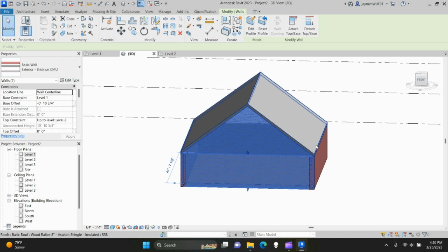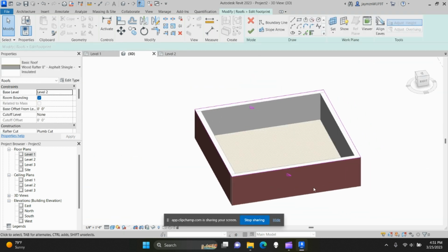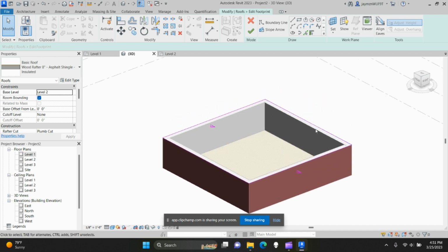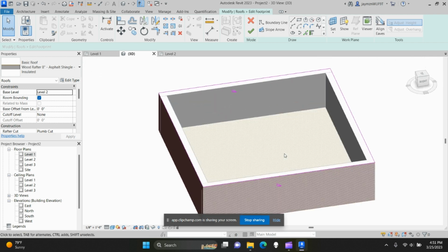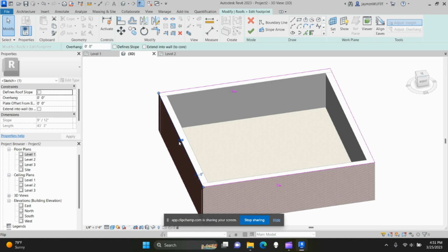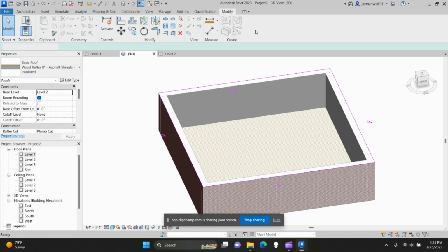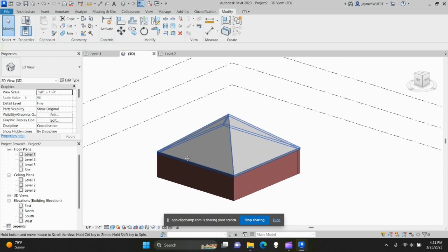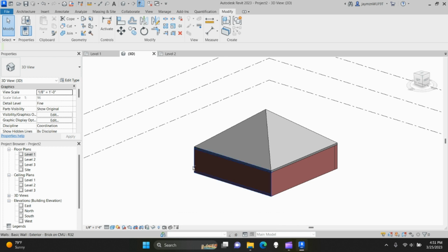So we're going to click this wall. I can go to the top here, just reset. All right, my recording cut off, but we're back. So as I was saying, we're gonna go back to the way the roof was. So I deleted that wall profile, set it back to the original, went into my roof editing. I'm just gonna click back on these walls, turn on my defining slope so I have a regular roof here, hit my check, and there we go. So that gives us now where I was going to end up at.